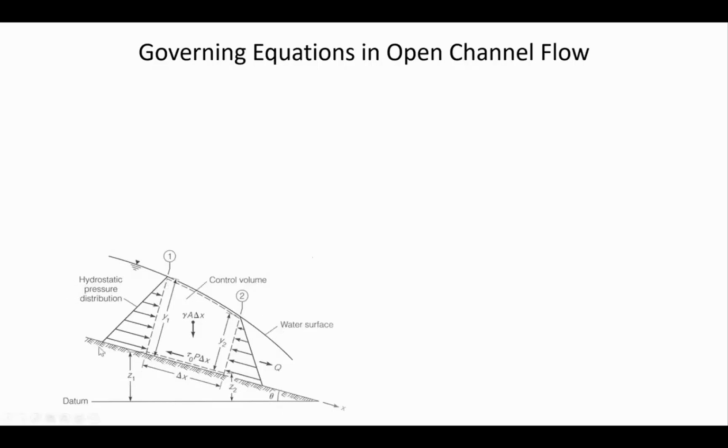Okay, so this side view, this is the bottom of the river, and we're going to do the control volume approach, where you take a certain element of water, and so this is the water surface. See the triangle and those little cross hatches there, that is meant to invoke the shimmering ripples of an open surface in contact with the air. So you've got a water surface, and you can see that the depth is decreasing in the direction of flow.